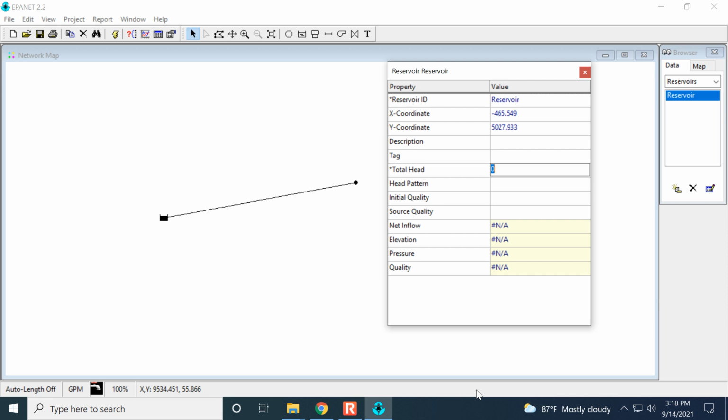And remember this word head, the technical interpretation of that is it's the sum of 3 terms. It's the sum of the elevation of the water, the pressure head of the water, and the velocity head of the water. And so in a tank, where a reservoir is essentially a really large tank, when you have water that is at the surface of the reservoir, it's not moving anywhere.